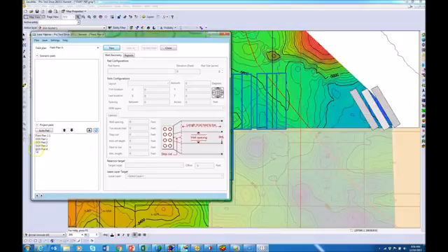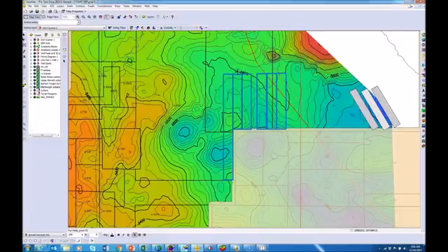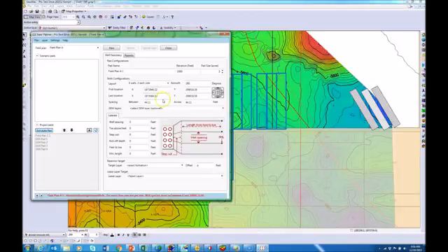Now I've got some other pads out here, but I'm going to use the Auto Pad feature to go ahead out here and click where I want the first slots to be. It captures the XY of the slots. I want 3 wells for those 3 well windows in each one of those. I'm also going to back interpolate from a digital elevation model the elevation of the pads.